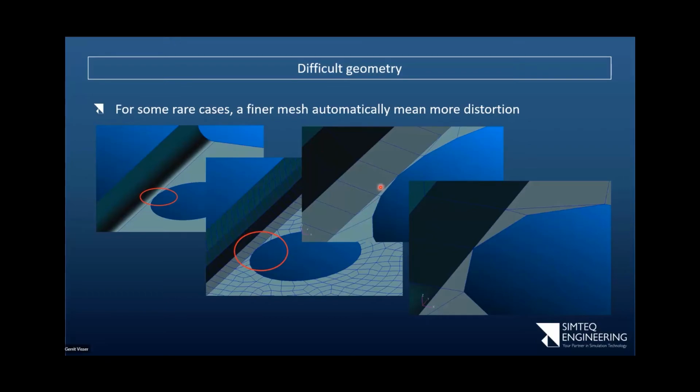Okay, now in this case, both of these are actually surprisingly okay, even that bad element there, simply because I allowed tri-elements in this model. If I force it to only use quads, there'll be a really horrible element in that location. There's no way that something like this can work.